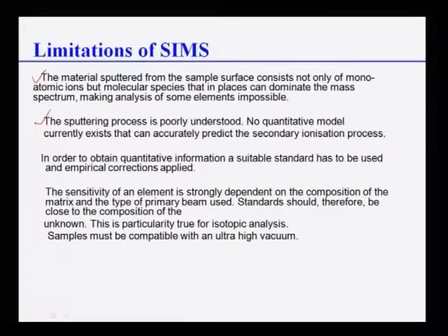The third thing is that to obtain quantitative information you need a suitable standard with quantitative information. That is the case for everything. In SEM, EDS also requires a standard. Also, the sensitivity of an element is strongly dependent on the composition of the matrix. Remember, you are putting the element in a matrix, organic matrix, liquid matrix.